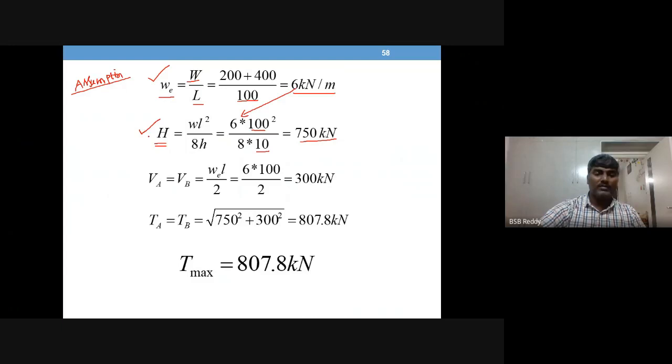Okay, got it. So all these unknowns are for the cable. You should get my point. What is the reason to take the cable first, against the three-hinged girder, where we started with the girder free body diagram? Here we don't need that, because the assumption that you make here will get your UDL value directly, so we don't need to use the girder first.